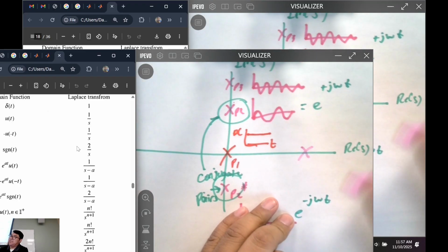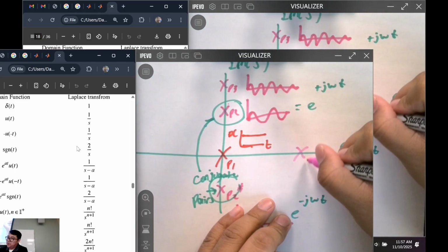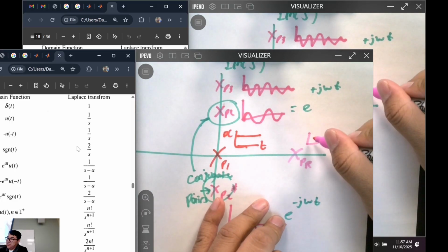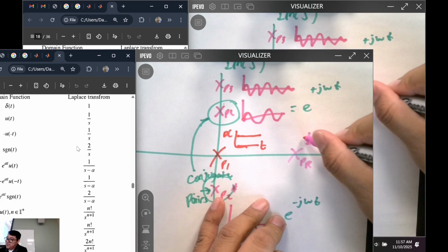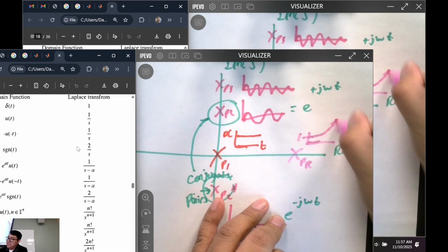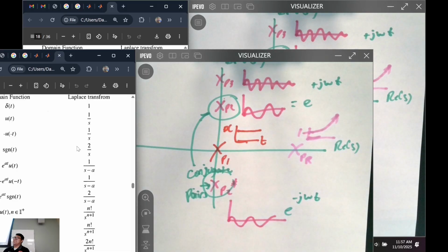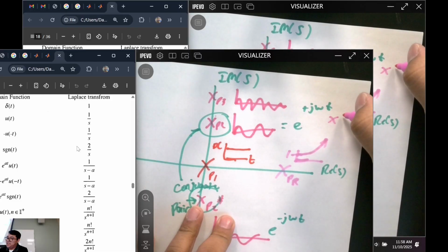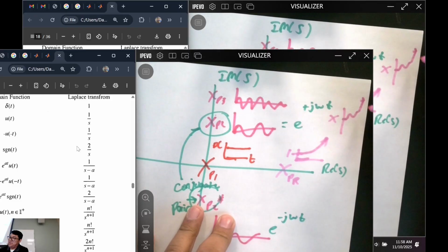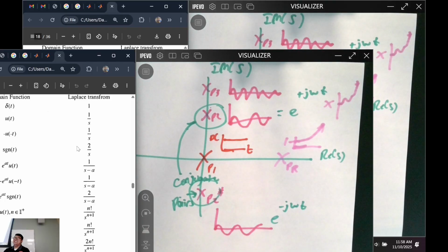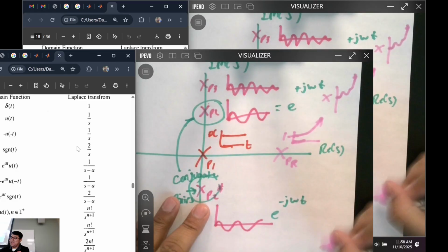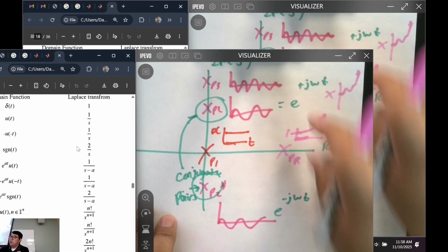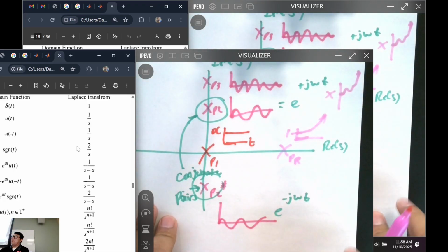I'm just going to put a pole right there, all right? Just a nice pole. Pole, I don't know, pole R. And this is just going to look like, well, like this. Well, it starts at 1 and explodes. Is that good? And then if I go above here, if I put the pole over here, it's going to be a wiggle that explodes. Is that good with everybody? And then the same thing is going to happen on this part too: you're going to have conjugate pairs, okay? When you have a pole that's imaginary, you need to have a complex pair.